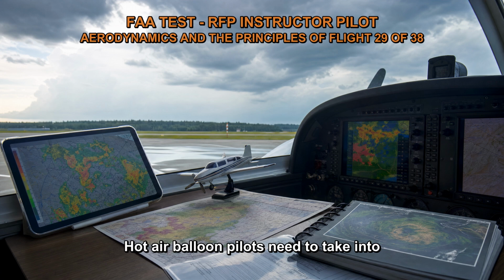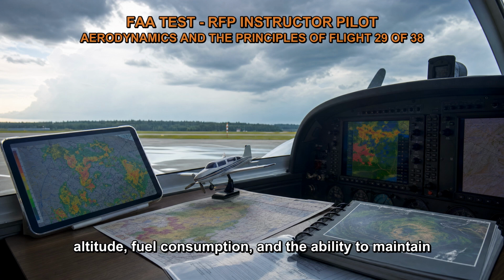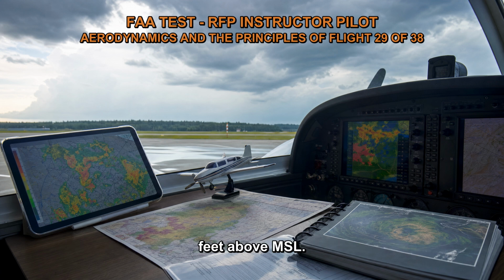Hot air balloon pilots need to take into account this decrease in burner efficiency as they plan their flights and consider factors such as altitude, fuel consumption, and the ability to maintain the desired lift and control during the ascent and descent phases. Therefore, the burner efficiency of a hot air balloon decreases approximately 4% for each 1,000 feet above MSL.